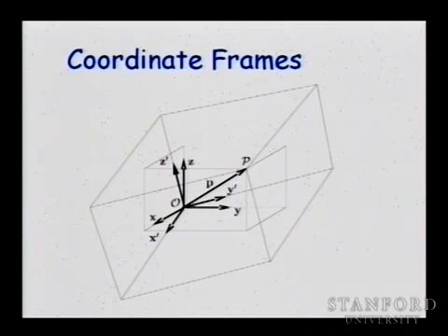And this is going to happen using transformations. Now, this transformation is just rotating the frame about the same point. But we might have a prismatic joint, and then we are going to translate the origin. So there will be a translation. So we need not only to deal with rotation in the frames, but also translations of the frame.